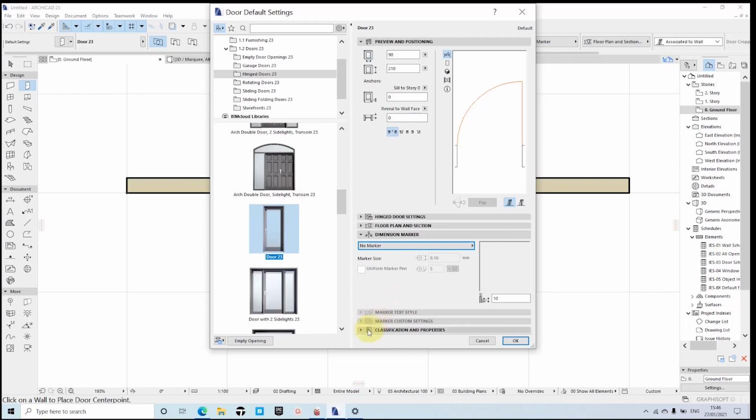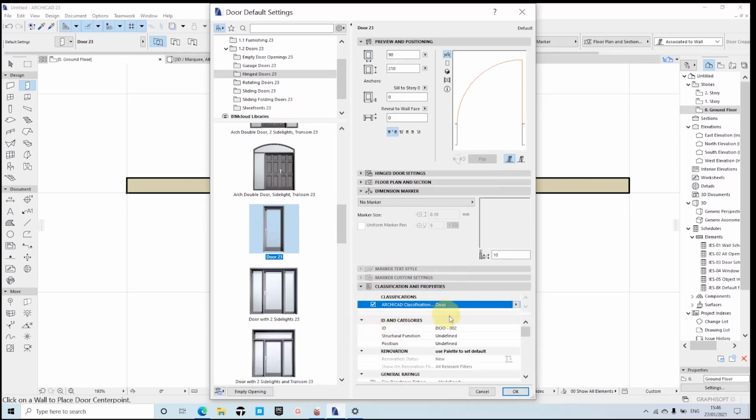project. We can also set the classification where you can put this type of door and all the information related to these doors, like setting if it is load bearing, non-load bearing, and so on. All these properties are available for such things. You can set things like the fire resistance, sound transmittancy, the product info such as the serial number, the production company, and so many things, the glazing and everything inside here.